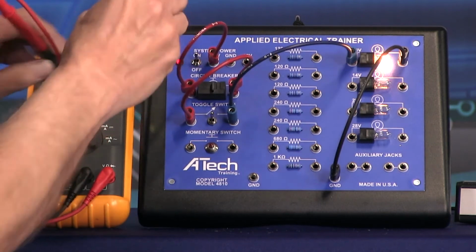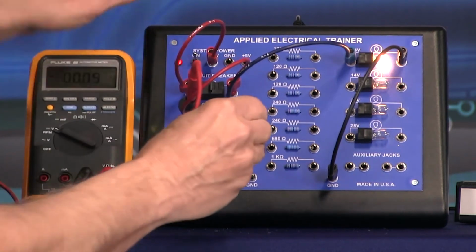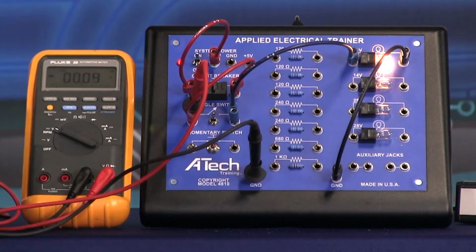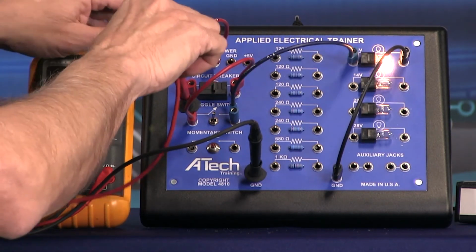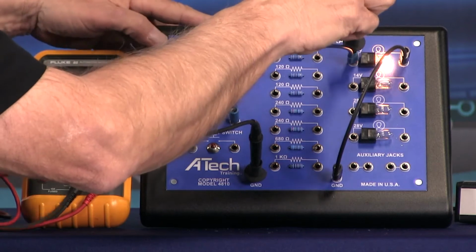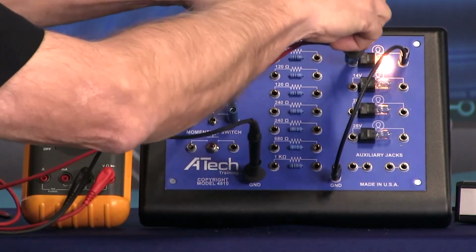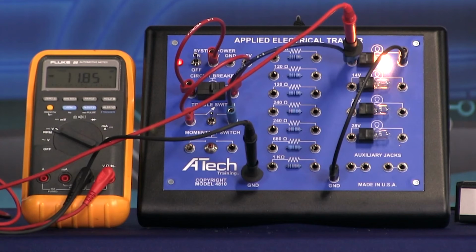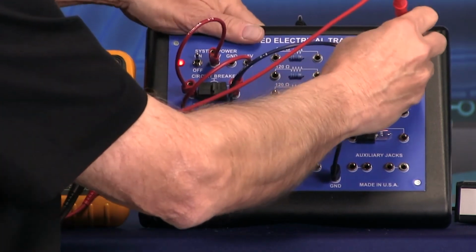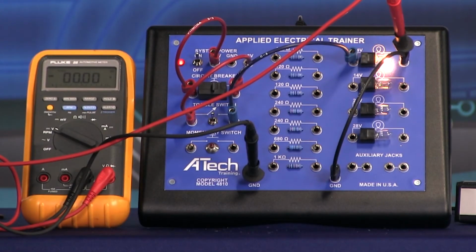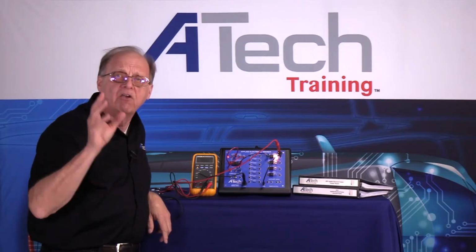So when I come over to this circuit, put my ground up there, notice if I got it right, I got 11.84. So I have dropped 0.12. And if I'm coming back over here and looking at it, I should have, if everything's good, 11.85 over in there. So we have a little bit of a difference, but it's still there. And then after that, if I'm looking at my circuit, notice I have 0.